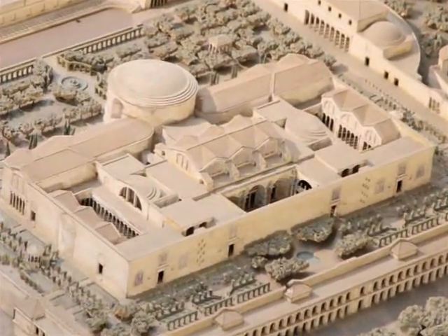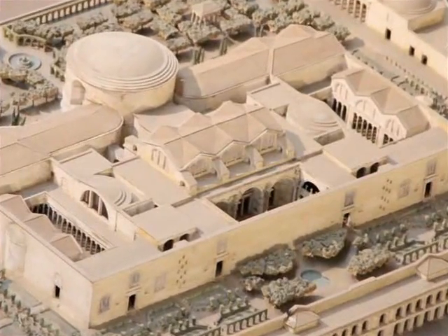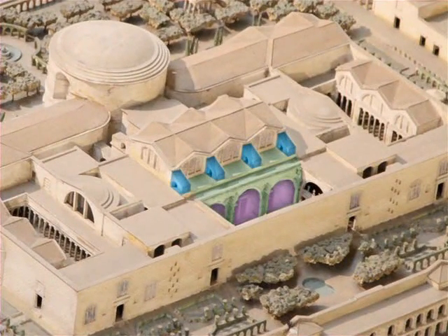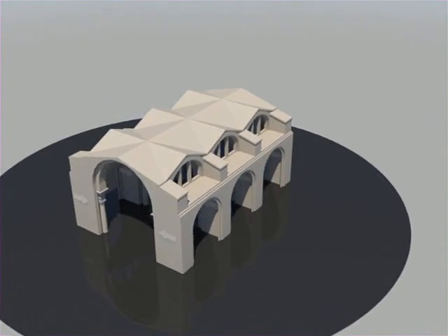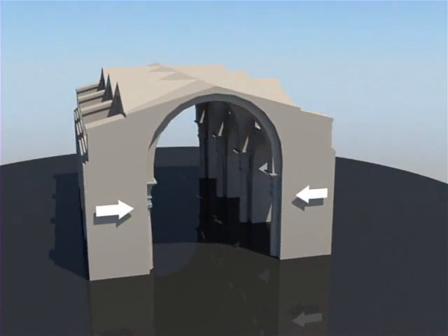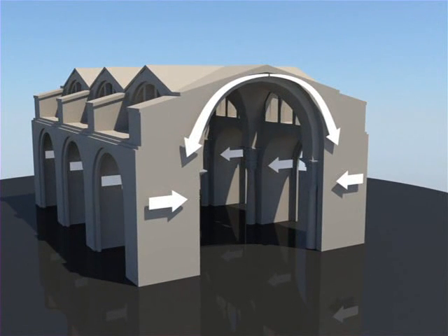The second technique that Roman engineers used to restrain the thrust of the vaults was an ingenious system in which smaller lateral barrel vaults were added perpendicular to the central space and used to prevent the central vaults from spreading laterally. This system of buttress vaults, as they're called, required a keen understanding of the flow of forces through a complex three-dimensional structural system. This innovation, yet another indicator of Roman engineering savvy, would be adopted in many future buildings, from Hagia Sophia in Constantinople to Filippo Brunelleschi's Church of Santo Spirito in Florence.